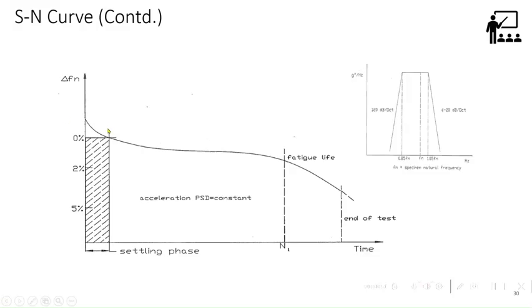So unlike in metal, where cyclic testing makes the specimen fail into two parts, in composite it will not fail. So the usual benchmark is, before starting the test, you take the stiffness, deflection per unit load, and keep on cycling until you get a 2% decrease in the stiffness, which is known as the failure. So that way you define your curve for the composite.